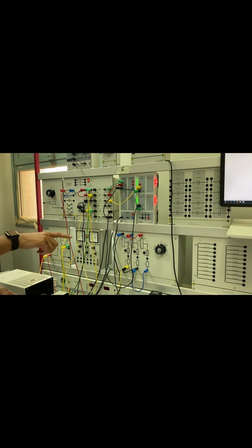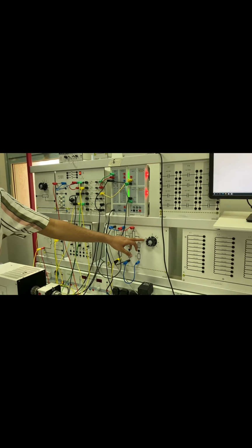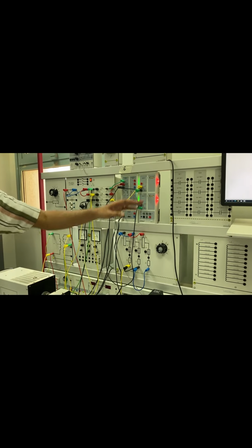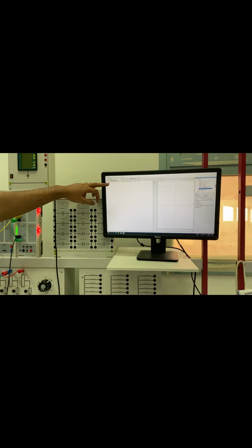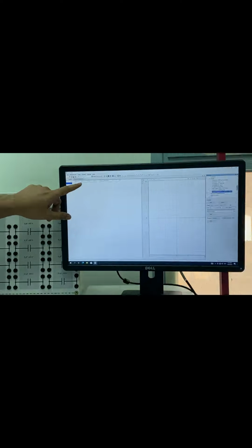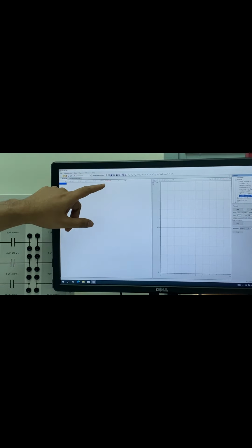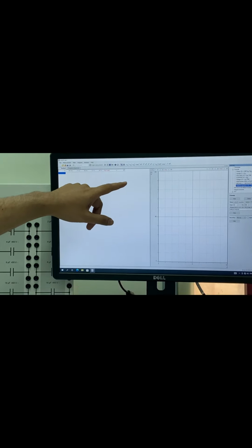How to take the data? We'll apply the voltage, and then for different percentages of resistance, we'll press F9. And that will give us, you can see here I have brought P in, V1, I1, V2, I2, P out, efficiency and voltage regulation. So whenever I press F9, it will give you all the data automatically, without doing any further calculation. It will give you directly. Okay. So before taking the data, do you have any question? Any part not clear? Okay, great.